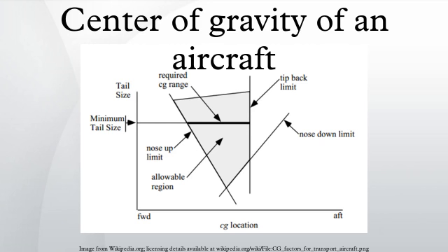Mean aerodynamic chord, a specific chord line of a tapered wing. At the mean aerodynamic chord, the center of pressure has the same aerodynamic force, position, and area as it does on the rest of the wing. The MAC represents the width of an equivalent rectangular wing in given conditions. On some aircraft, the center of gravity is expressed as a percentage of the length of the MAC.